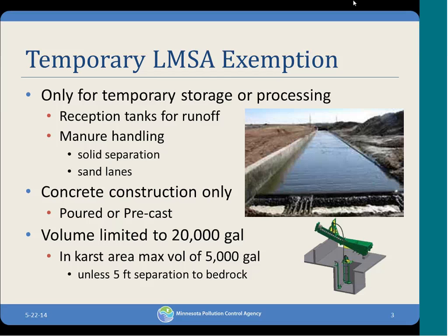Yeah, unfortunately, it is what it is now. The basin is intact. I would encourage them to discuss it with their pumper. Maybe they could try getting closer. Do they have a concrete chute? It does have a ramp, correct? Yeah, so maybe getting closer to the ramp, it's kind of hard on it, but at least then you're spinning against more concrete.